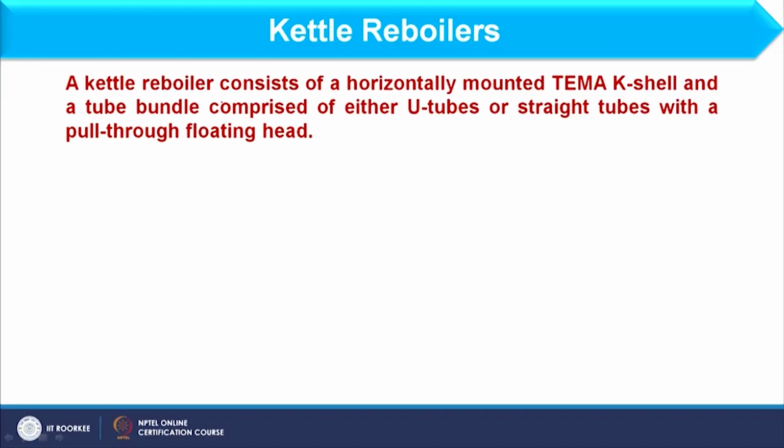In the same line we consider the kettle reboiler, because in this, whatever liquid is available which is to be converted into vapor, it is entirely covered by the heating media. As you see in a kettle, the heating media is merged in the fluid. Therefore, it is named the kettle reboiler.